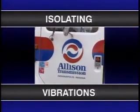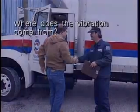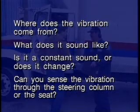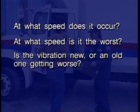When you're assigned a truck with a vibration problem, you should first ask the driver these questions. Where does the vibration come from? What does it sound like? Is it a constant sound or does it change? Can you sense the vibration through the steering column or the seat? At what speed does it occur? At what speed is it the worst? Is the vibration new or an old one getting worse?